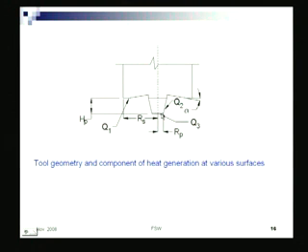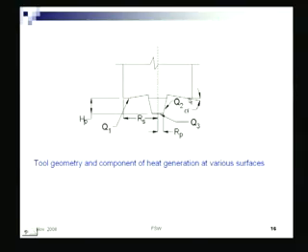First, the bottom surface, this flat part it touches, then this surface of the nib, and then the shoulder. And here the shoulder, once it is concave, does not generate any heat, because that is not in contact immediately. Only when some metal is getting expelled, if it is, then there will be some contact. Otherwise, the shoulder at the periphery, which is flat again, is making contact.